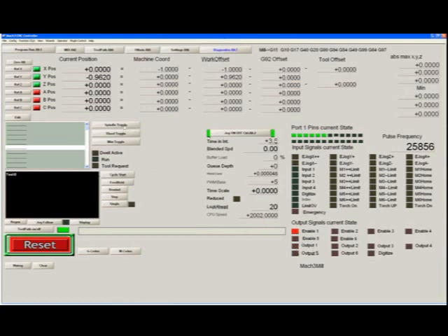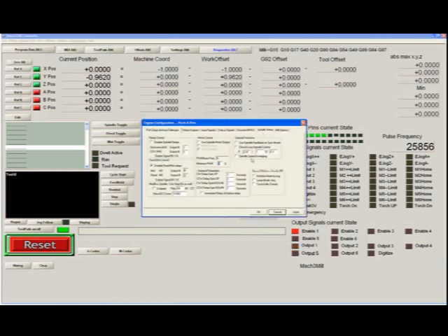Now you'll notice whenever I toggle the spindle on, we get a dwell active, just for a moment, and it shuts off. If we look at the configure ports and pins and go back to the spindle, you can see here under general parameters we have a spin up delay and a spin down delay for each direction. This is the number of seconds that it's going to take before the relay shuts off and before the system allows any G-code to continue.